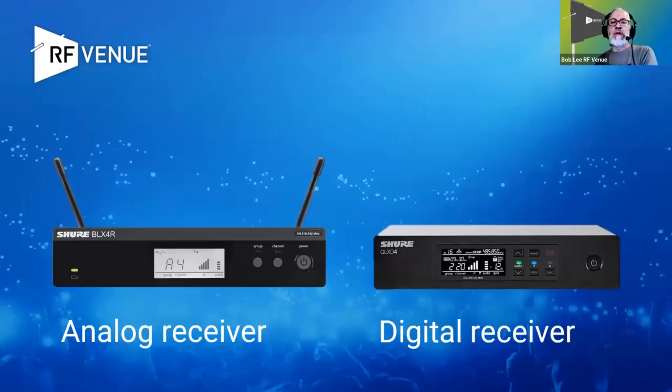So an analog receiver down converts its RF signal to an intermediate frequency. So you have an FM signal that's then at a lower frequency, and then that goes into the demodulator. Typical intermediate frequencies are like 10.7 megahertz or maybe double that, 21.4 megahertz. They're popular. These are just standard things that have been developed for FM radio for decades. If you look inside a consumer FM radio, you'll typically see 10.7 megahertz as an IF stage.